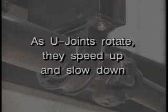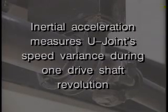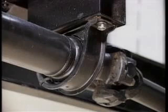As driveline U-joints rotate, they speed up and slow down. This is an inherent design characteristic of all U-joints. During one complete driveline revolution, each U-joint will speed up and slow down twice. Inertial acceleration measures a U-joint's speed variance during one revolution of the drive shaft. Too much variance can cause U-joint damage. The U-joint must be within inertial acceleration limits.